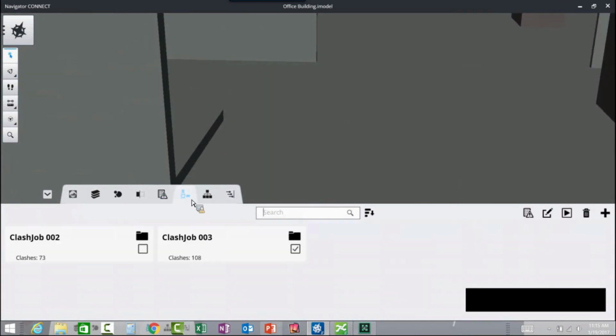And what we'll see here is that because we turned that off, different things that are touching in the model are actually being picked up as additional clashes. So that's why it's important to have that particular suppression rule on in the process.